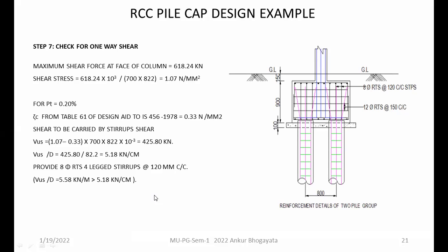Whether it is a foundation, then you have to go for 2 types of shear checks. Whether it is an RCC beam, an ordinary beam, you have to go for the ordinary shear check by means of shear stirrups. If you are designing columns, then you have to go for the horizontal thrust and the buckling requirements. So ultimately, only 3 jobs have to be done for any RCC design, right?